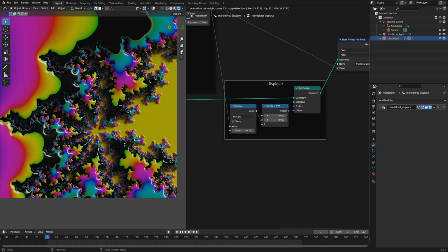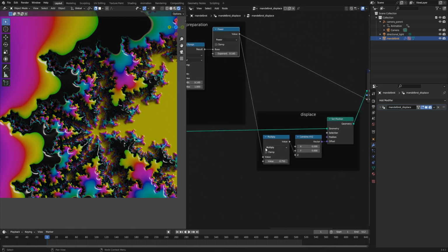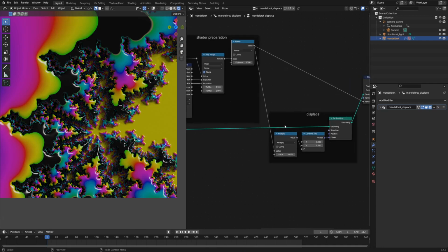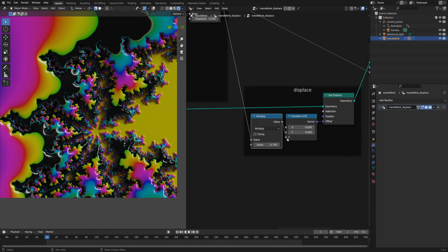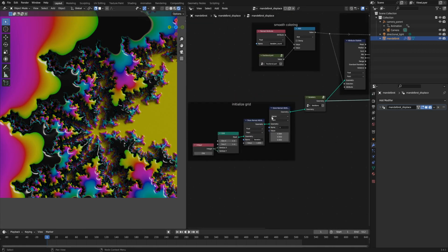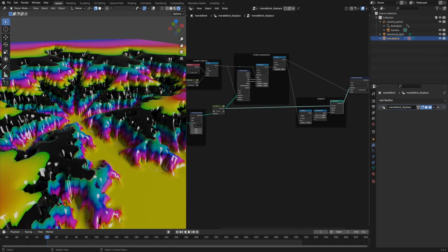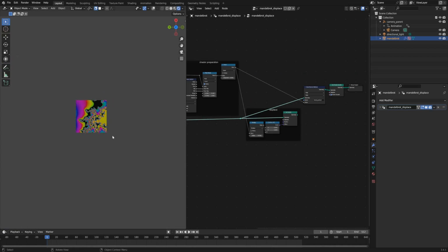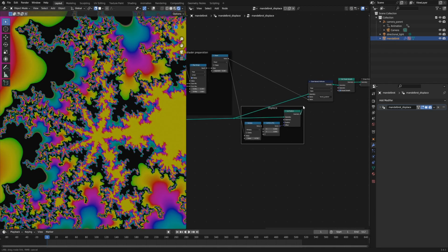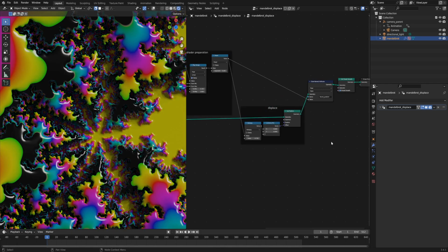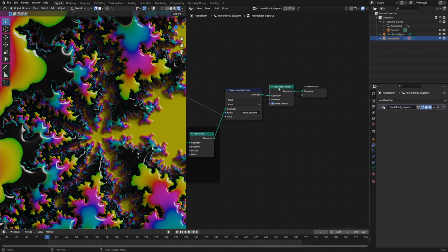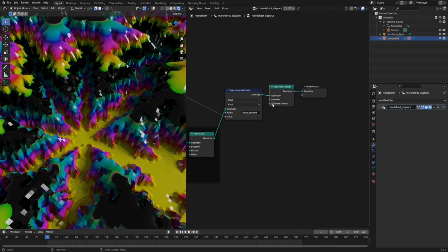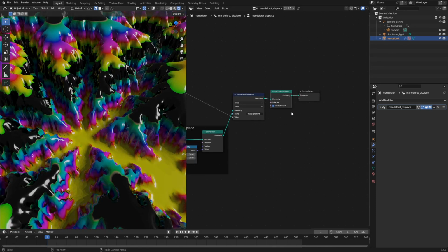And lastly, there is this displacement frame, which simply does further transformation with a multiplication node on the output of this power node, and then uses that value as the z component of a vector that offsets the positions of the grid geometry to create the displacement effect. Without that, you'd get the coloring changes, but you wouldn't get any of the displacement. So let's rehook that up. The last node in this network is the set to shade smooth, which we do because it looks nice. And now we can move on to the shader nodes.